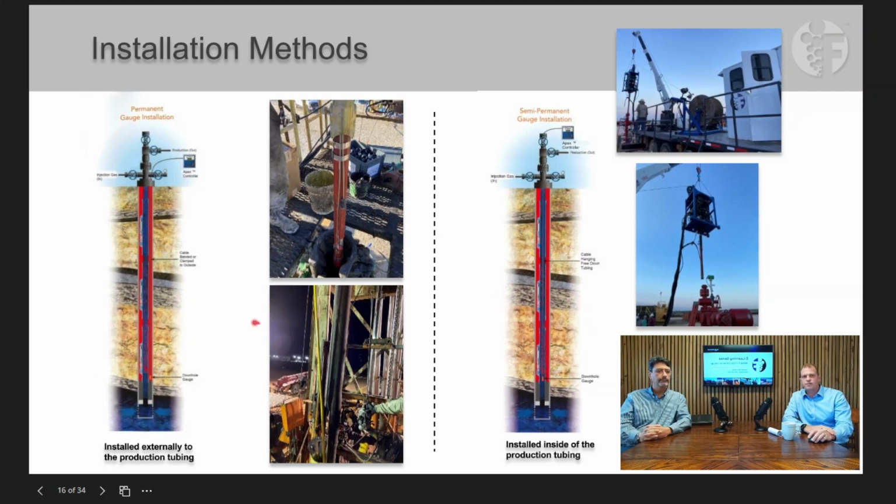Yeah. And again, one thing mentioned too is, depending on the artificial lift types, you would pick your different installation methods. Like if you had a sucker rod pump or a PC pump, of course you'd have to go external installations, right? Because you're going to have your rods and your pump internally. Correct. But if you had a natural flow or an EOR injector project, or even a gas lift, you could pick between external or internal based off well environments and applications. Correct. Yeah, that's absolutely correct. Okay, perfect. Thank you, Juan.